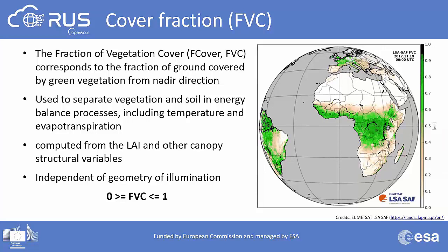Canopy cover also determines how much rainfall is intercepted by the vegetation before hitting the ground, which in turn affects the rates of evapotranspiration, erosion rates, and consequently it is important in hydrological studies. It can be measured using the same methodologies used for optical measurements of leaf area index. The canopy coverage is simply 1 minus the total gap fraction.